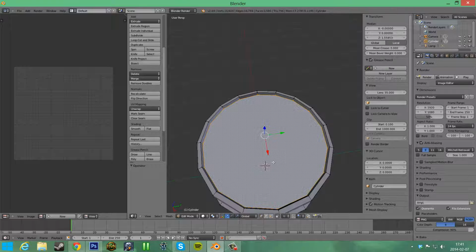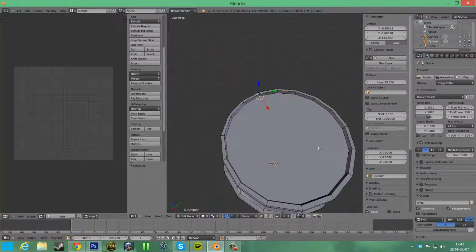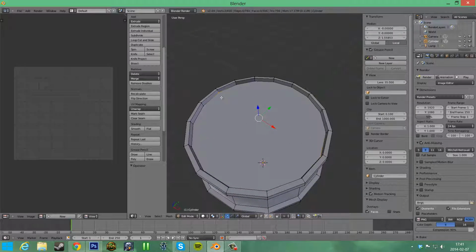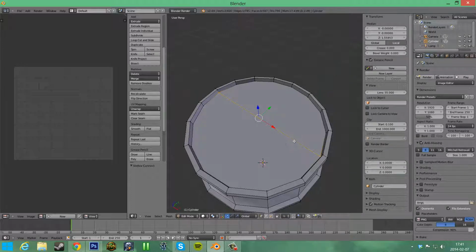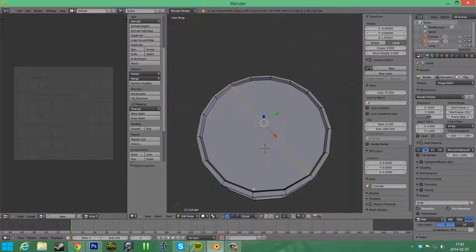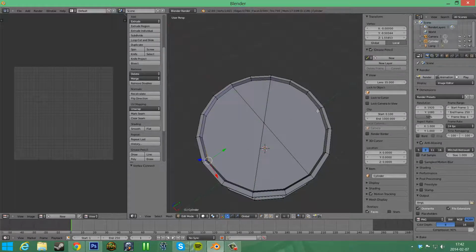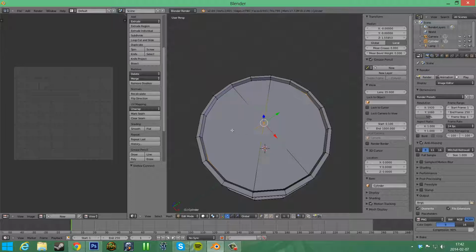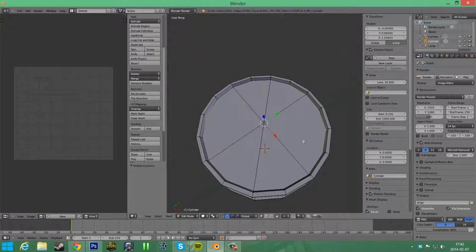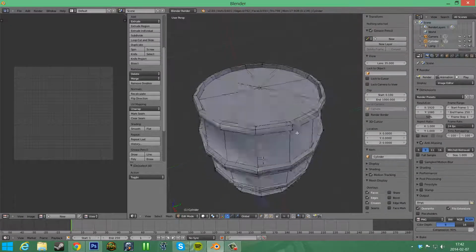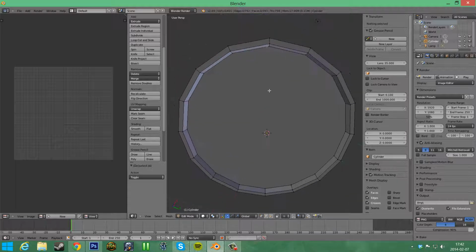Then we can select this edge loop here, or actually no, don't do that. Just press this polygon tool, and then we're gonna create our own quads or triangles. Press these two and press J. So now we made a line between them. So now we can press these, make a line, these, make a line, and there. So now we made a quad. So 1, 2, 3, 4 vertices are connecting with this face. And let's do the same on the back side.